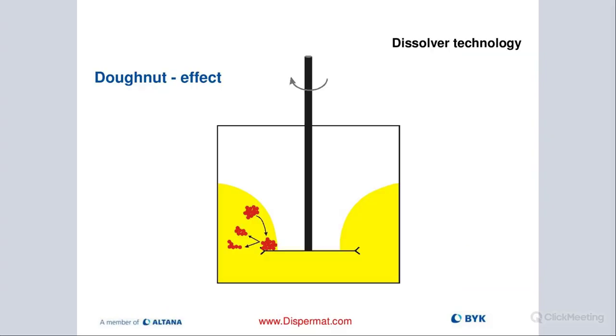What happens there is, as the blade spins at those high RPMs, the particles hit the edges of the blade, and those sharp teeth really start ripping up these binding forces and separating those particle classes and reducing them to the aggregate level.